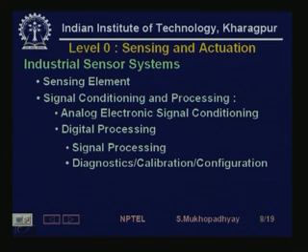This is a very modern functionality. If you have a microprocessor, you have a lot of computing power at your hand. So, you can do more than just filtering. You can, for example, perhaps detect whether the thermocouple wire has broken, whether the sensor is at all functioning. So, that is diagnostics.